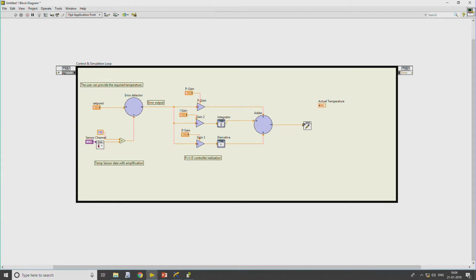So I have connected it here, but we cannot directly connect. The reason is that since it is a simulation, the system can even provide an infinite amount of data as an output, but in reality the data acquisition device cannot provide very high magnitudes. Each device has limitations with respect to the operating voltages as well as current. Even with the USB devices, the output voltage it can generate is 0 to 5 volts. Since the simulation can go above 5 volts, both positive as well as negative, in order to not have any conflict between the values, we can create some kind of threshold such that if the input voltage is greater than a particular value, send the output as a maximum.